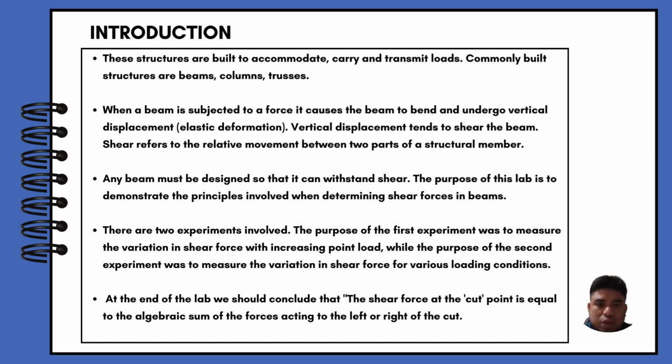Vertical displacement tends to shear the beam. Shear refers to the relative movement between two parts of a structural member. Any beam must be designed so that it can withstand shear. The purpose of this lab is to demonstrate the principle involved when determining shear force in a beam.